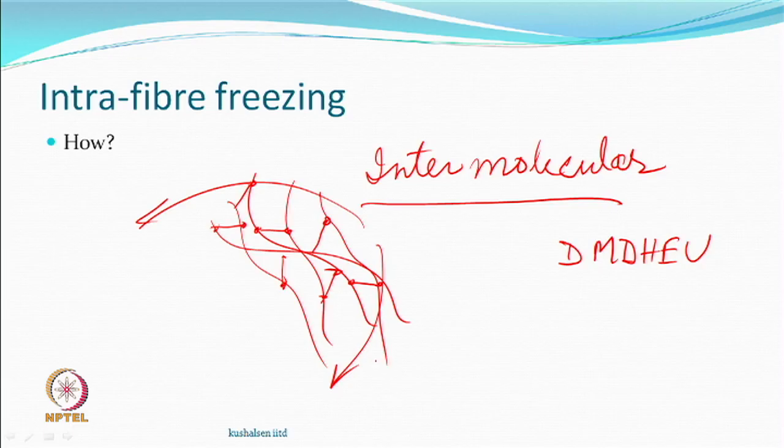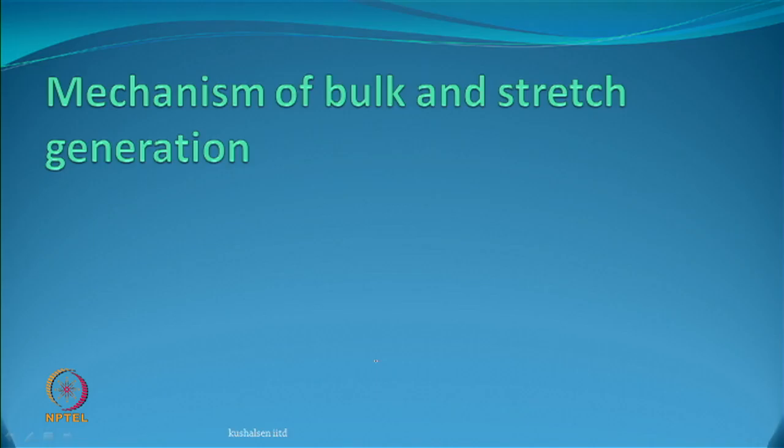So, for texturing, I may say that we may like to have intra fiber, because each fiber or filament we want to behave individually and not get stuck with each other. In a multifilament yarn, if all filaments are stuck with each other, how will it give me stretch and how will it give me bulk, right? So, this is what we may probably be requiring.